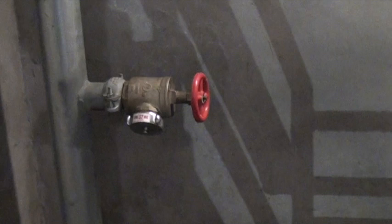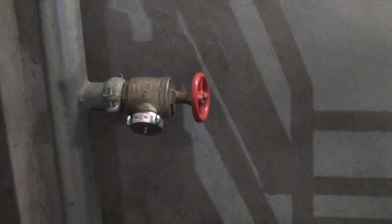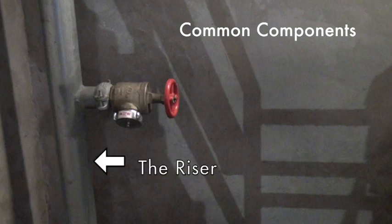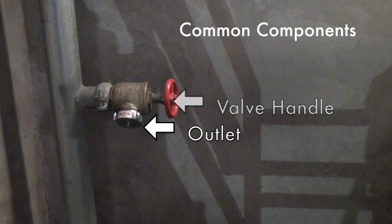An important note: Montgomery County Executive Regulation 19-13, entitled Fire Protection Systems, prohibits Class 2 and Class 3 systems from being equipped with hose for occupant use. Each standpipe system may have a slightly different configuration or layout, but the common components should include the riser, a hose valve, an outlet, a valve handle, and a cap.